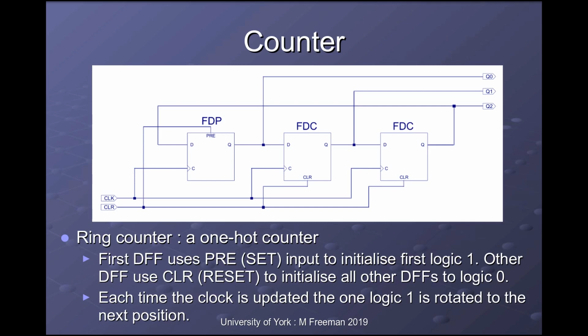Also, as discussed previously, binary, as in a base 2 representation, is not the only binary representation, so we can represent other values within our system using one-hot encoding, and we do exactly that inside the control logic. And for that we'll be using a ring counter, as discussed here.